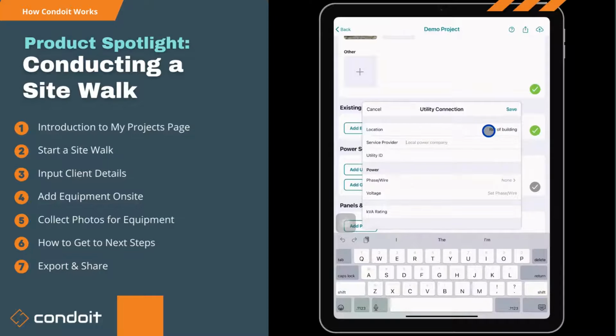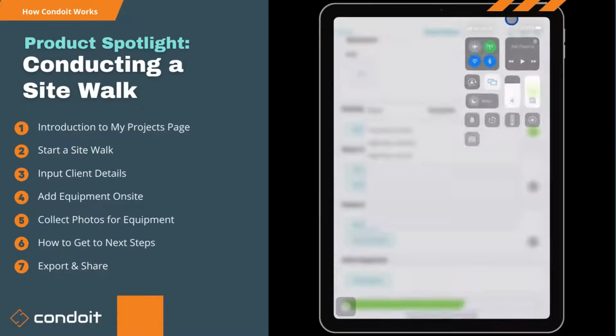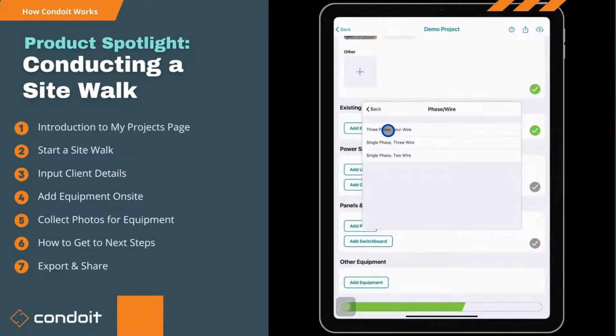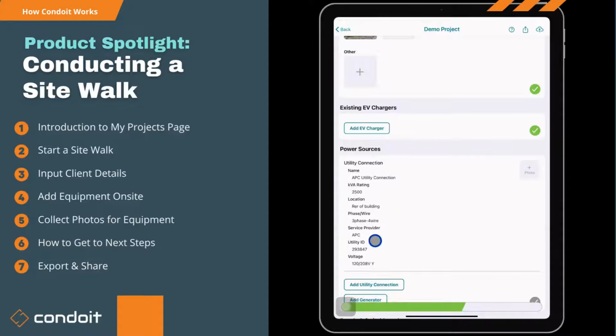Service provider, around here it is Alabama Power Company, so we'll say APC. You can pull the utility ID off the meter. The phase wire distribution, we'll say that this is, for instance, 3-phase, 4-wire. And we'll say it is 120/208 volt Y. We'll say, for instance, maybe 2500 kVA. Save that. So we get our utility connection, all of our details.